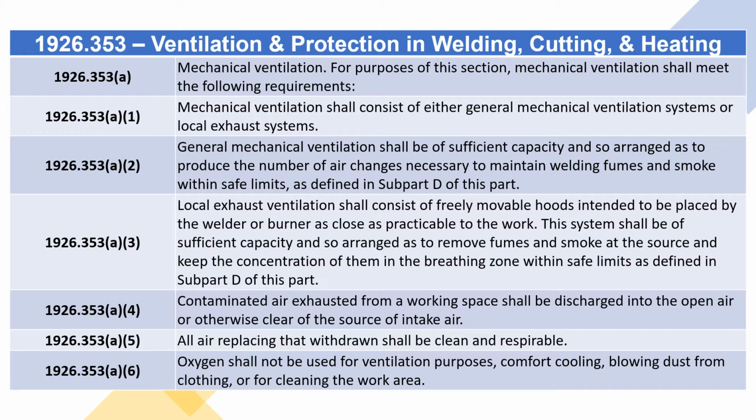A.2. General mechanical ventilation shall be of sufficient capacity and so arranged as to produce the number of air changes necessary to maintain welding fumes and smoke within safe limits, as defined in subpart D of this part.